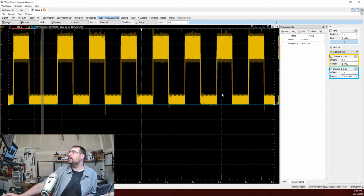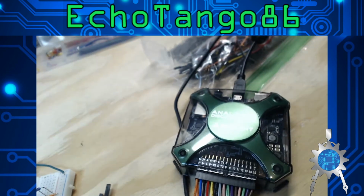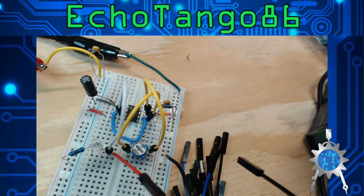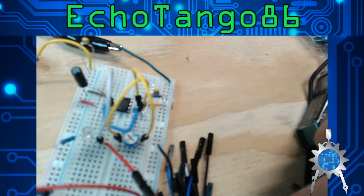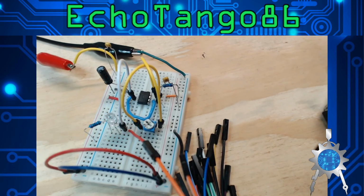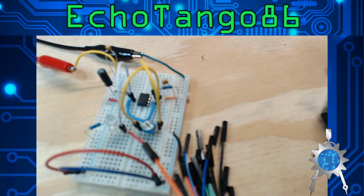But we'll go ahead and show you how to hook it up so you can see from your oscilloscope what you're dealing with. So we'll change the view here to the circuit. I'm using a thing called Analog Discovery 2 by Digilent. Hope I pronounced that right. And we used the first wires, and we did our ground, and then we probed the end that is at the output. So every time that light turns on, it's showing a pulse high, and then it goes up onto our screen and gives us the ability to see the oscilloscope. So those are the 2 wires we plugged in from there. Ground and then our output on the IC chip.